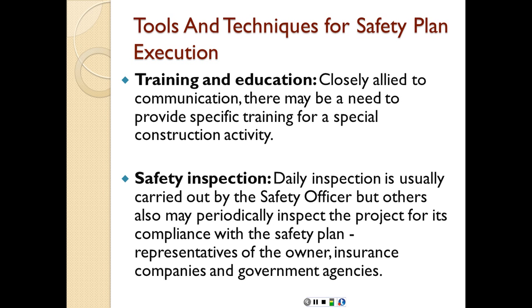Safety inspection is going to include daily inspection, which is usually carried out by the safety officer, but others also may periodically inspect the project for its compliance with the safety plan. Representatives from the owner, the insurance company, and government agencies, such as OSHA, for example, have the right to inspect to make sure that you have good safety measures.